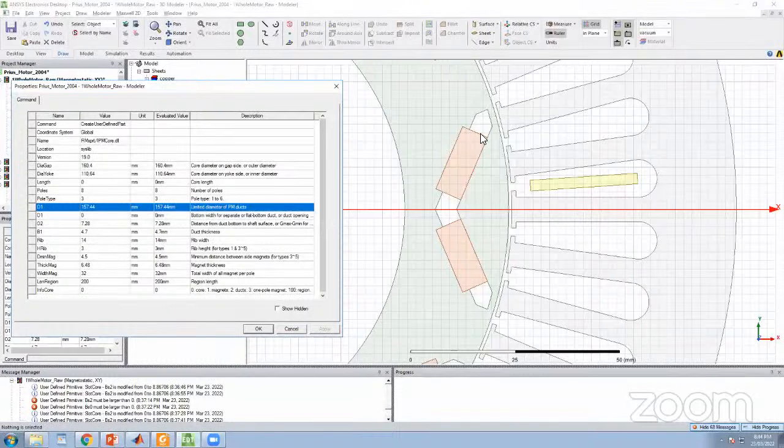The waist of the magnet, 32, which is the waist of the magnet here. Okay. And you can see the magnet is actually thicker, or higher than the magnet slot. Okay. That is because we need this part as a stopper, to secure the magnet at its designated position. Okay, so once you insert the magnet into the slot, it can't move. If you don't have this stop, it may move up or move down. Okay, so this is how you build the rotor structure.